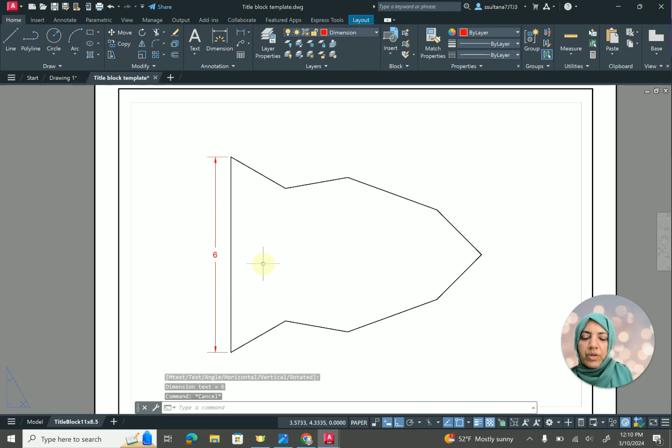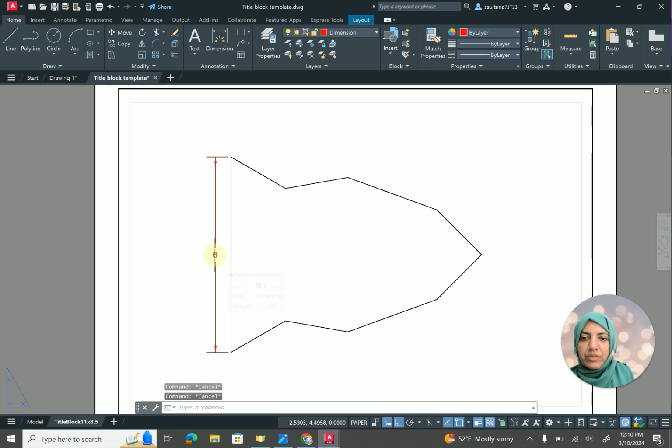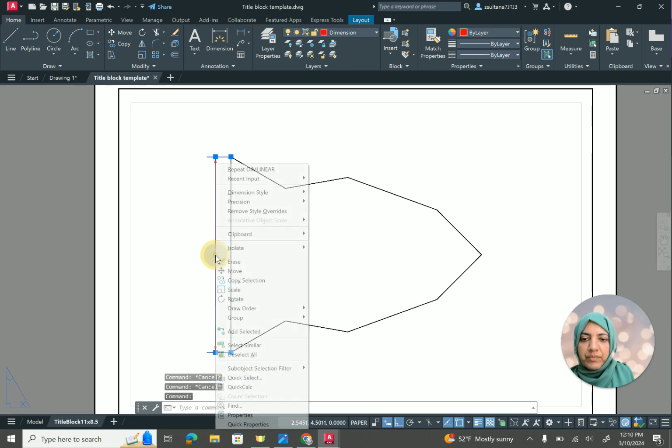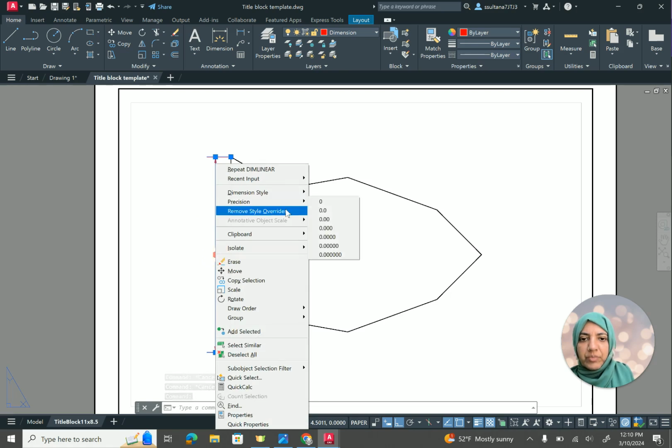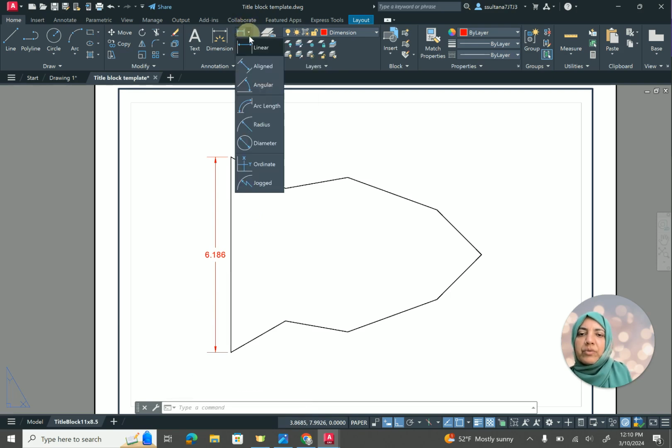In this case, rounding down. All the other numbers are whole numbers except for this one. So in this case, we are going to right click on it and change the precision locally, because this one has 3 decimals, but all the rest are just whole numbers. So we are not going to do that globally.